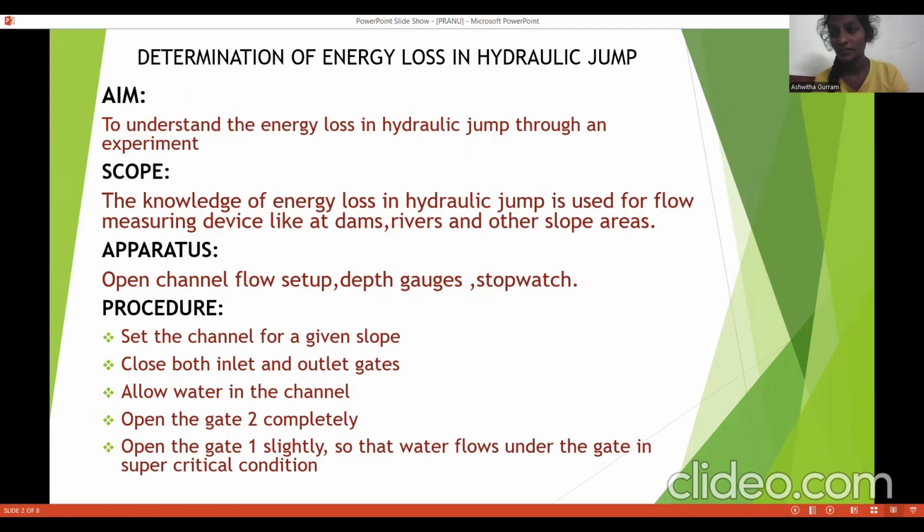The water surface slope becomes infinity at the critical depth. The water surface tends to become vertical, which is manifested in the formation of hydraulic jump. The hydraulic jump occurs where the bottom of the channel changes from steep to mild slope and below the control structure.